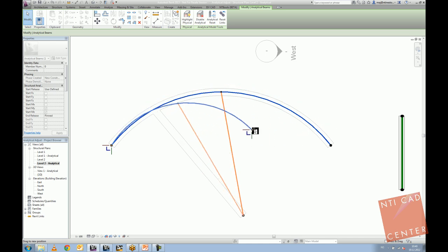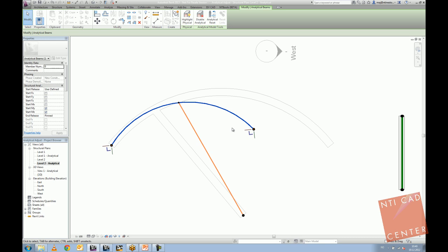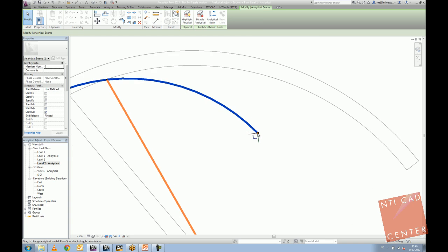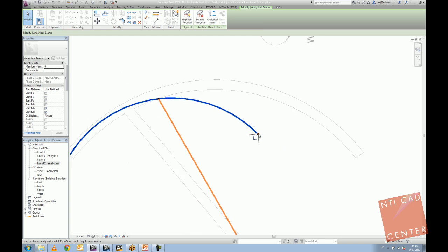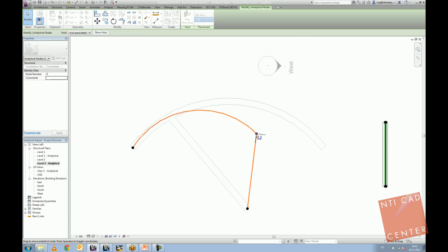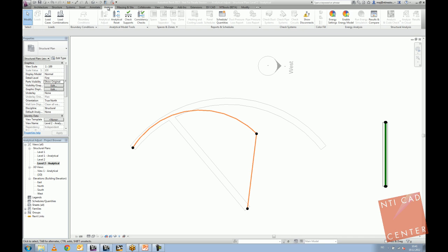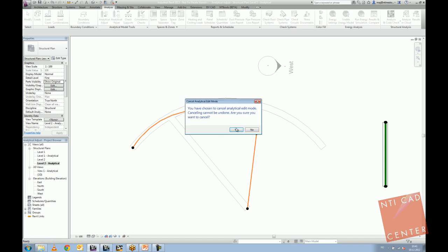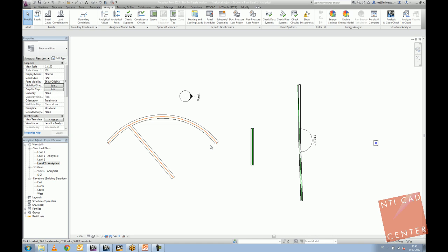So again, in some cases you really want to select several offsets with equal distance. That is very helpful. Or in some other cases, for example, I have a hard time when I need to connect all of the elements into one node. Then it would be just simply selecting that node, hosting it to the element, and saying, please go to the 0 point. So then I'm 100% sure that this element will always be at the start of the element, so that the nodes will be exactly at the same point, and no gap will be there in between. Again, really nice functionality which you can utilize. We will go back to this analytical adjust slightly later now. I'm just going through the rest of the examples.